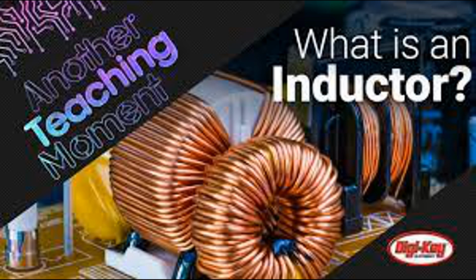Induction heating. Application: Resonance circuits are used in induction heating systems, where high-frequency currents are used to induce eddy currents in a conductive material, generating heat. The resonant frequency ensures efficient energy transfer for heating applications. Example: Induction cooktops and industrial induction heaters use resonance circuits to generate high-frequency currents for heating metal objects.